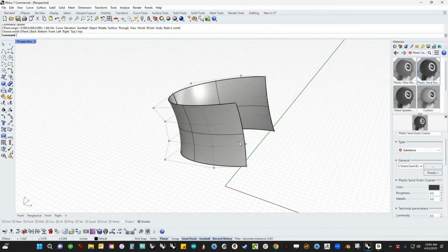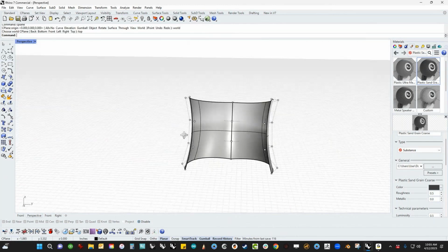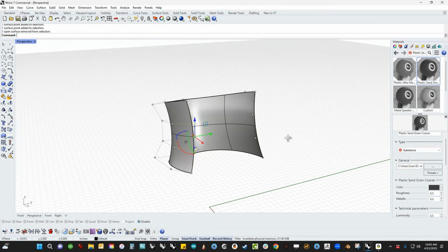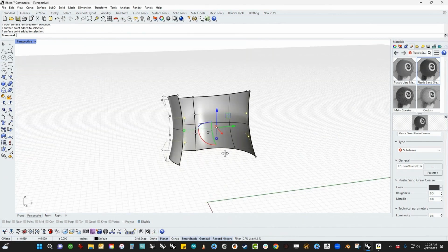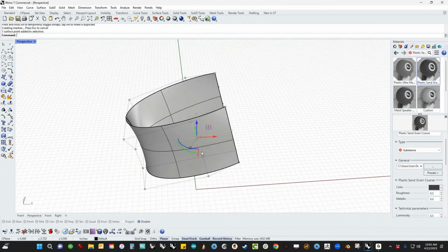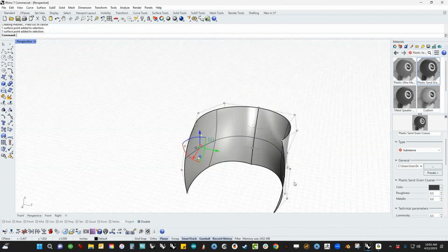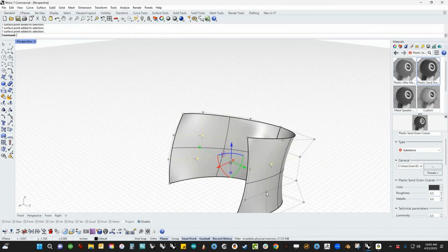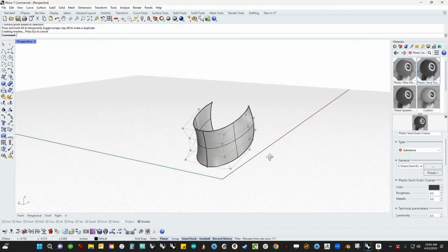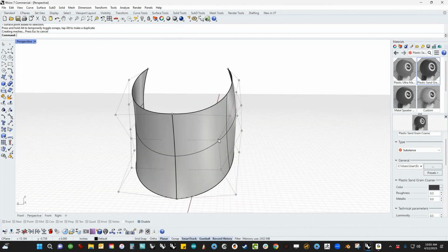And then the main thing that we need to fix is this tucking in. So let's grab these two. This is like one of the coolest things about NURBS. If you haven't done models where you've gone in and started pulling on the CVs, I would really, really encourage you to do so, because this is really where the power of being able to do surfacing comes from, because you can really, really manipulate this stuff to do exactly what you want it to do.